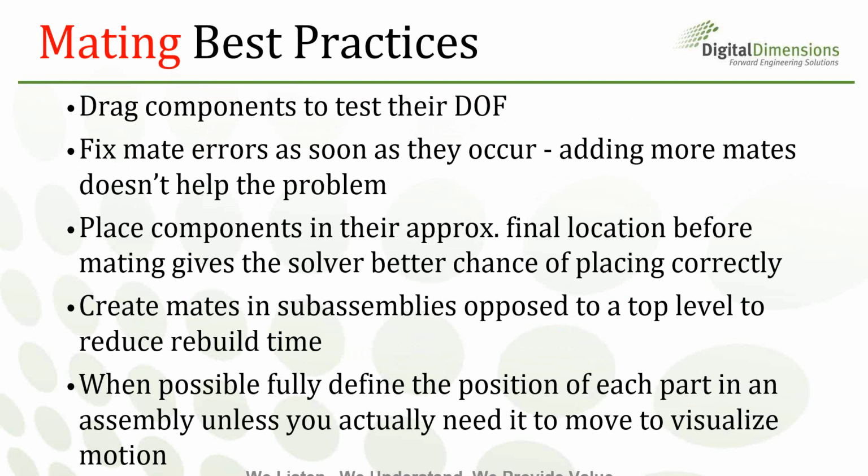And then when possible, fully define the position of each part, unless you're going to need it to move to visualize motion, do some kind of simulation, or check clearances or something like that. If you constrain all your degrees of freedom, that will definitely help when rebuilding.